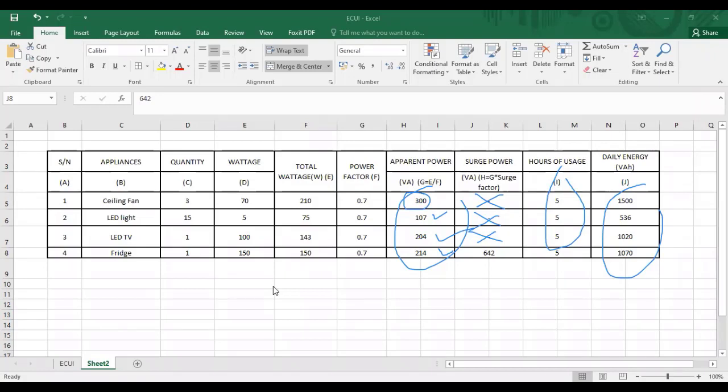So that's why I was using the beer analogy to explain. So you want to ensure that the power factor of your system is close to 1. Because if you have a lower power factor, that means your system is inefficient. If it's a generator, that means you will be consuming more diesel, and that is more cost to you. That means your device is not efficient. Instead of producing more, you are now producing less and you are spending more. So can you see why your power factor needs to be as close to unity as possible? Did I answer your question?